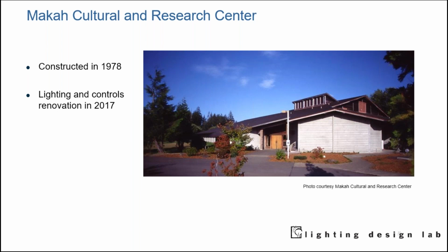The display cases were engineered with internal fan coil units underneath each one of the display cases to bring in filtered fresh air, which was exhausted out the top of the cases into the high open ceiling. Each case had its own thermostat to control the case temperature and the fan coil speed. It sounds workable, right?